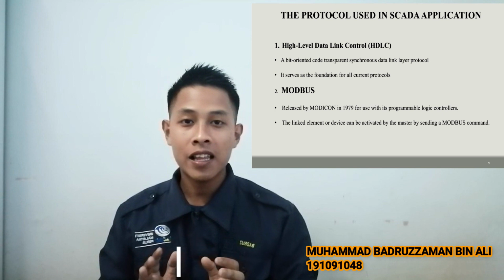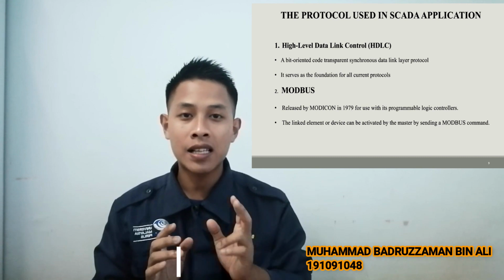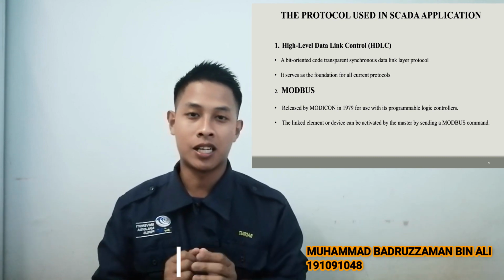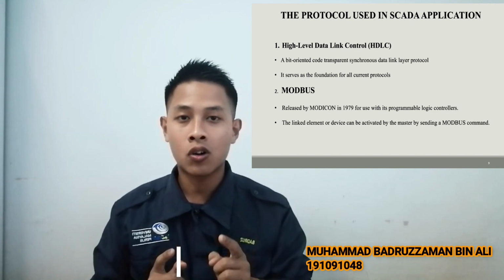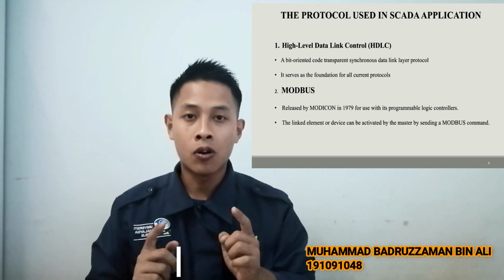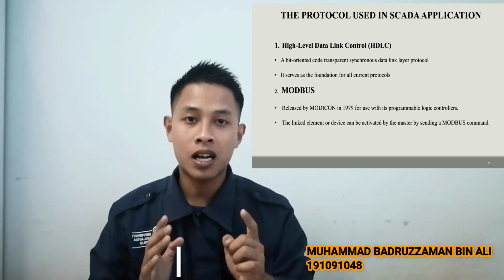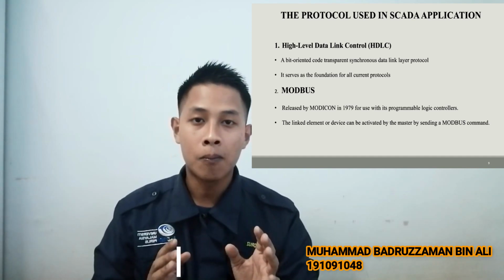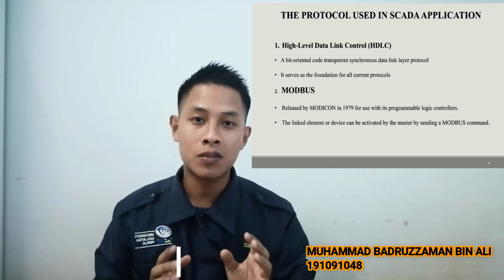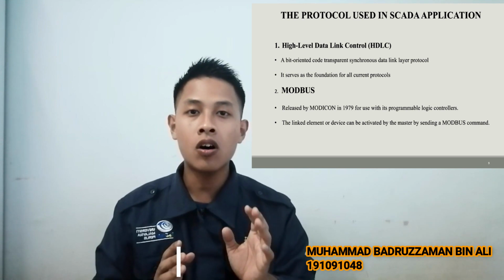Next part, the protocols used in SCADA applications. High-level data link control, HDLC, and Modbus are the two extensively utilized protocols for SCADA applications. A bit-oriented, transparent, synchronized data link layer protocol called high-level data link control was created by ISO. Both connection-oriented and connectionless services are offered by HDLC. Although HDLC can be used for point-to-point and multi-point connections, synchronized balanced mode, which uses a one-to-one connection, is preferred. It serves as a foundation for all current protocols.